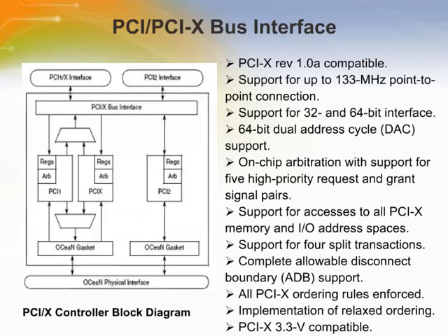The PCI-X Bus Controller acts as a bridge between the PCI-X Bus interface and the Ocean switch fabric. The PCI-X Bus Controller connects the Ocean to the PCI bus, to which I/O components are connected. The PCI bus uses a 32 or 64-bit multiplexed address data bus, plus various control and error signals. The PCI-X Bus interface supports address and data parity with error checking and reporting. The integrated processor's PCI-X Bus interface functions both as a master and a target device.